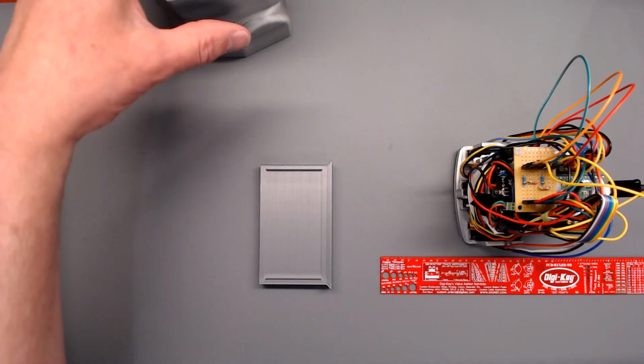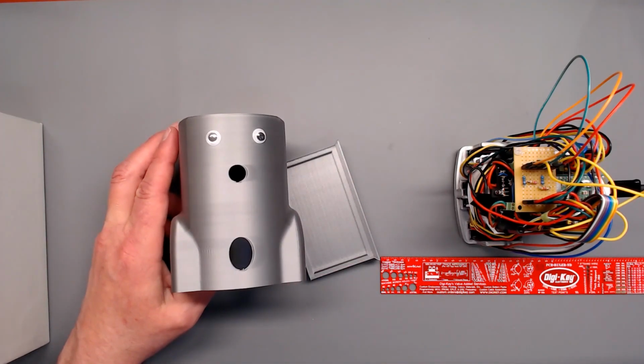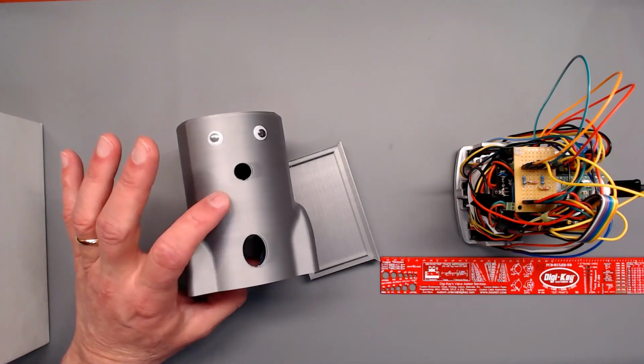Now, the one thing with time-of-flight sensors that I've learned over time is that they can be color sensitive and they can be texture sensitive as to how repeatable they are between different objects. One of the reasons why I've picked this silver color for the Zoomie bodies is that I want this and this to have the same reflective surface, same texture, so that I can get consistent readings between a Zoomie and these barriers, because those are the two most critical objects I need to detect.